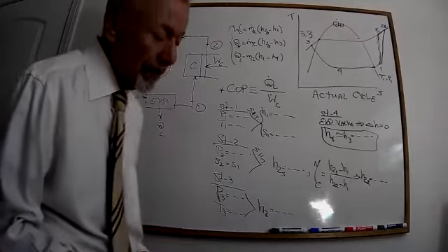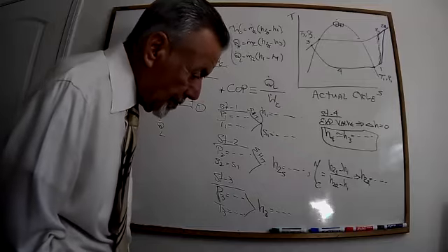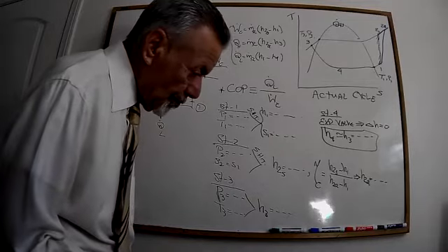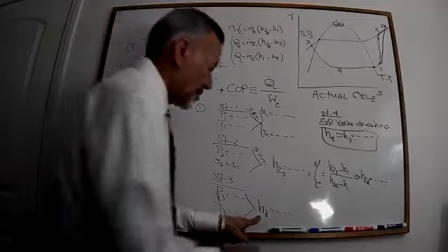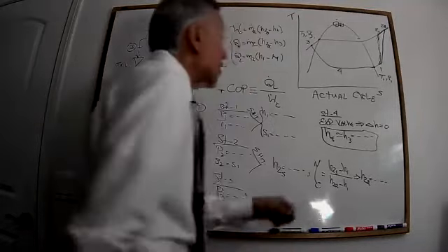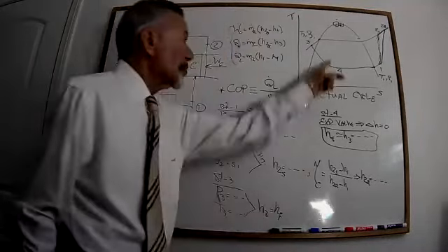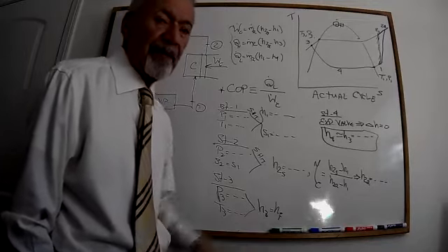Professor? Yes. So just so I understand, when it comes to point 3, when we have the pressure and the temperature, when we look for H of 3, it's going to be H of F for the value? The H3 would be H of F regardless of whether it is in saturated liquid or compressed liquid, that would be H of F from the saturated liquid table. Oh, okay. Thank you.